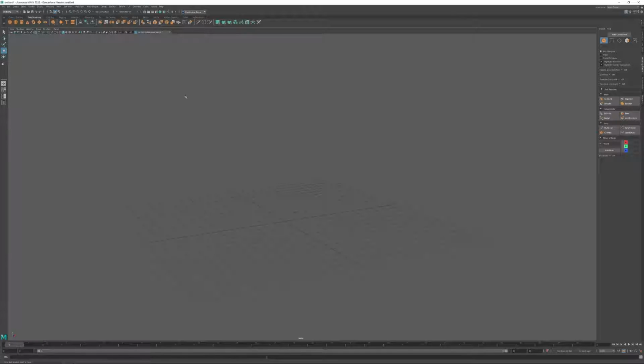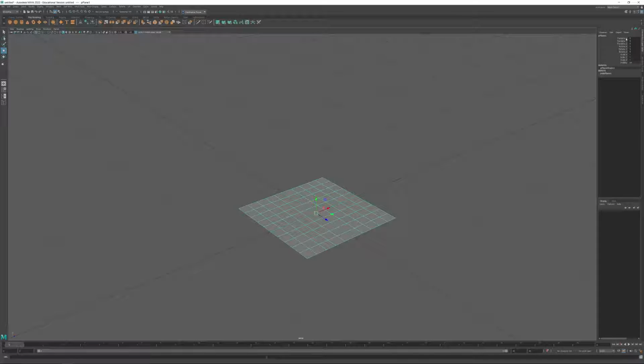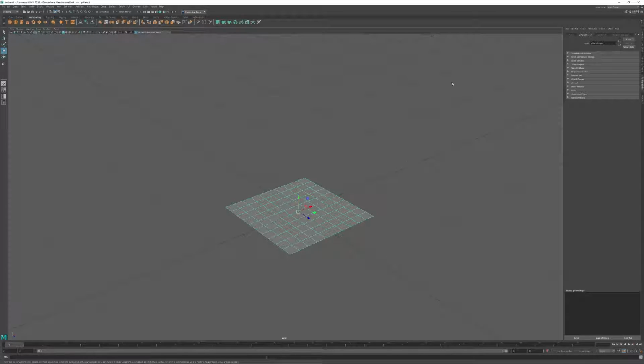To begin with, I'm going to create a plane. When I click on the plane tab, a plane will get generated at the center of the world using the default template that Maya has for all 3D geometry, in this case for 3D planes. If I head over to our channel box, we can see that there is no information in translate and rotate, and scale is set to 1. If we head into the attribute panel, we can see the construction defaults for this object. I'm going to leave the shape and enter the polyPlane tab. This gives us our default construction for this object.